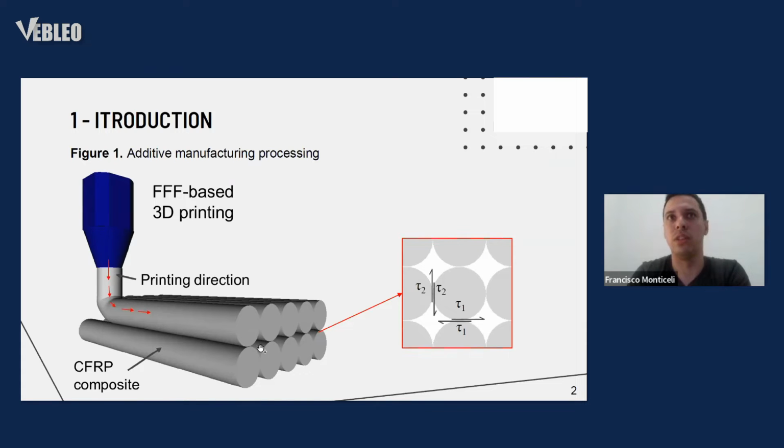Just for information, usually for the conventional composites for structural application, we have the concern to have lower than 2% of porosity, of void fraction. And in this kind of material, we usually have 2% up to 15%. It's too high for application. So the work we are performing is to avoid this kind of defect.